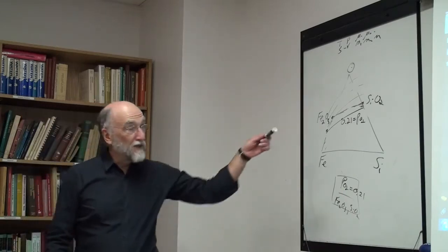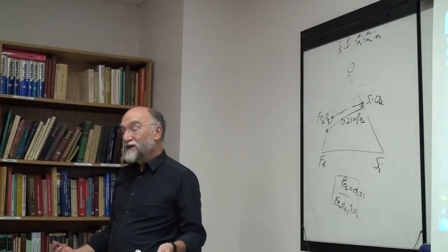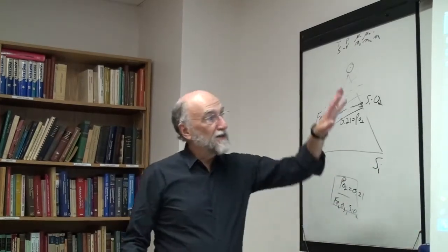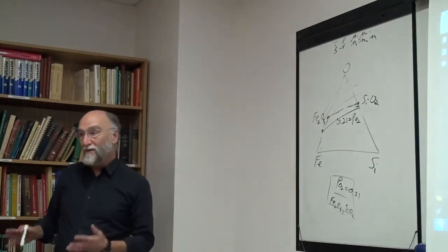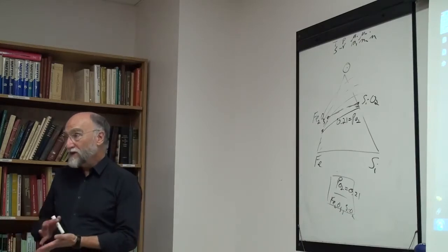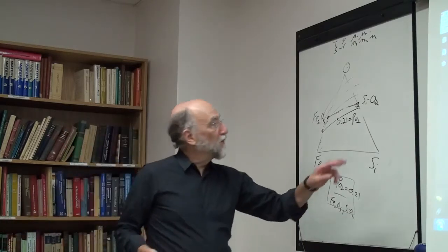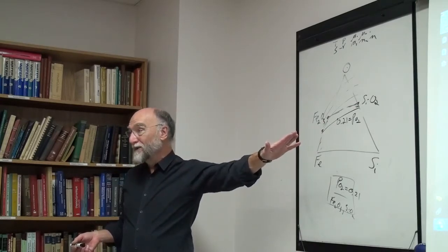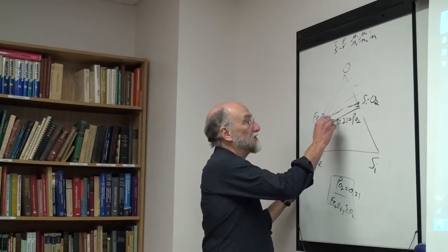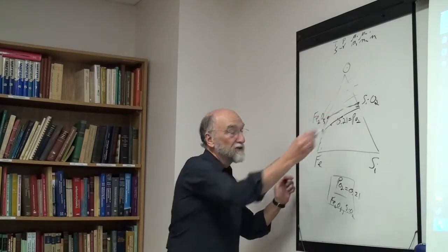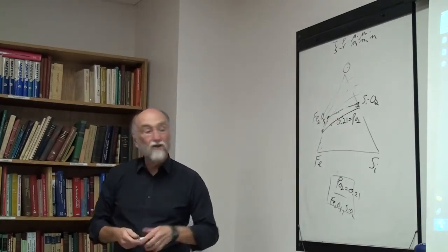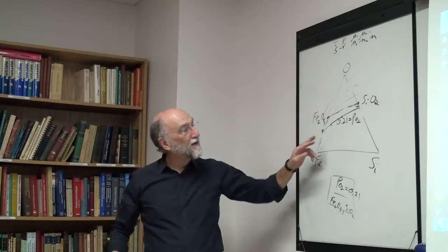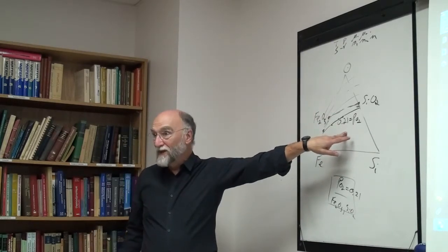Because it really has three components for sure. And the phases are not along this composition line. But it has exactly the geometry of a binary phase diagram, and the reason being that when PO2 is constant, all phases have to have the same PO2 at equilibrium. Okay, so necessarily then all tie lines lie on this curve. This curve is not an isopleth, it's not the Fe2O3 SiO2 isopleth, it's a curved line, which is a constant oxygen pressure line.